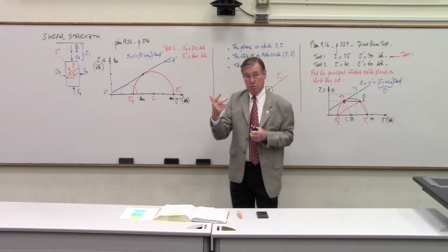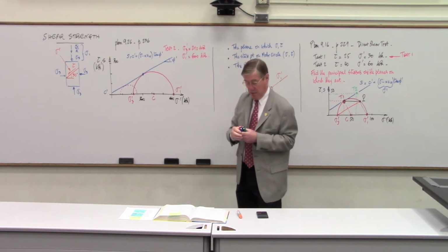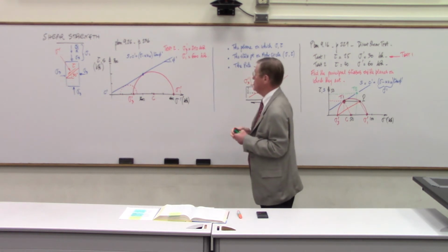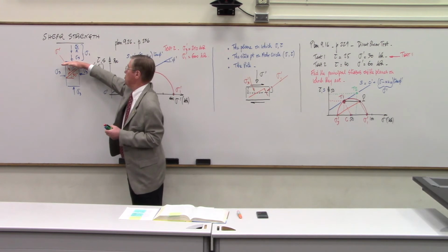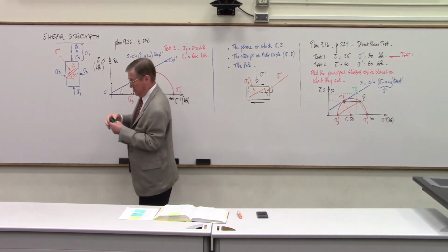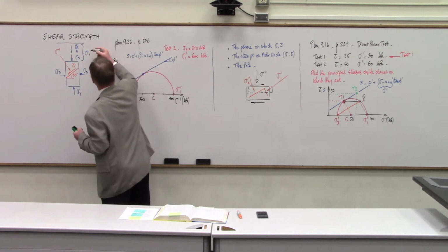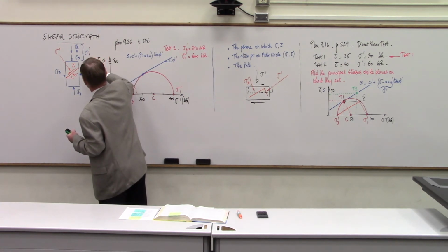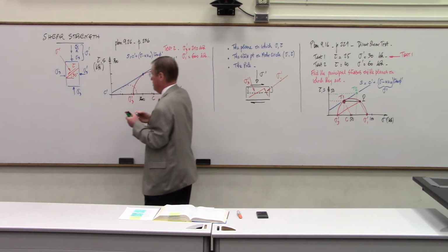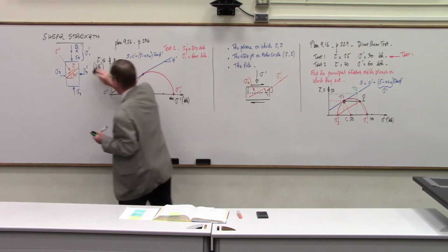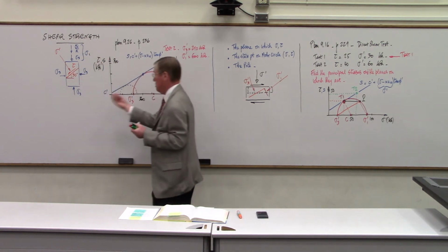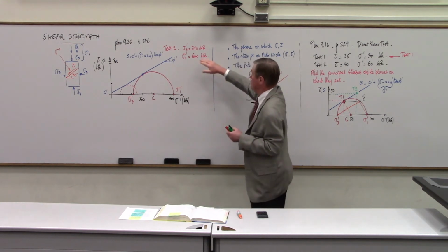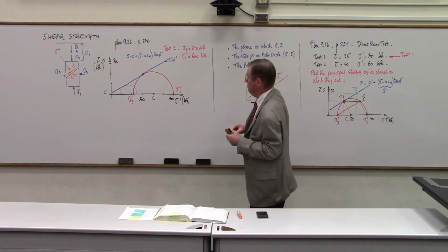We don't know the pole, we've got to find a plane and a stress point that we know. Well, we know that we have a horizontal plane here, and sigma prime 1 is acting on that. Actually, these are total stresses, but you have the pore pressure inside, and that's what we did in answering those questions before.